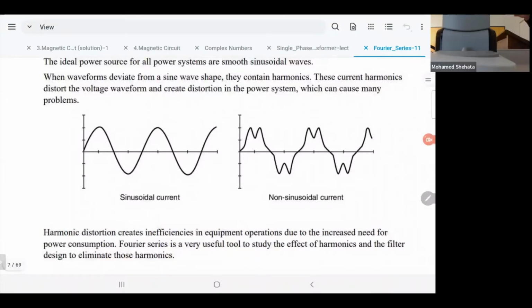Then we get 3-phase sinusoidal waves, pure. And the power is delivered to the customers, or in engineering terms, to a distribution station that will deliver to the houses, to industry. Then we have loads, like appliances, and that's okay. But we still have loads we can call non-linear, because we have electronic appliances. Electronic appliances have electronic switches which turn on and off, so it's like chopping the waveform, and it causes distortion in it.